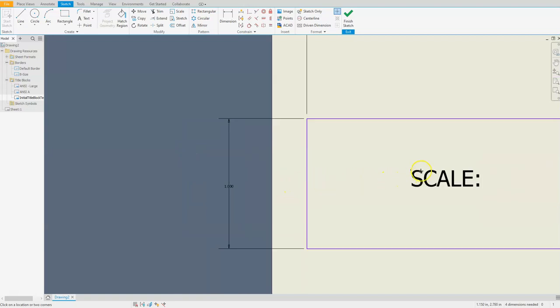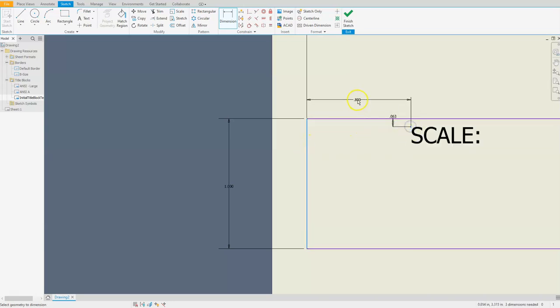If you take a look at that text, you can see that there is a node at the top left corner of it. Let's go ahead and place some dimensions on that. So I'll dimension from here to here. And I want that to be 0.0625. So 1/16 of an inch. I'll do the same going this direction. It's the exact same number, so I'll go ahead and select that dimension and you'll see that it will place my text where I want it.